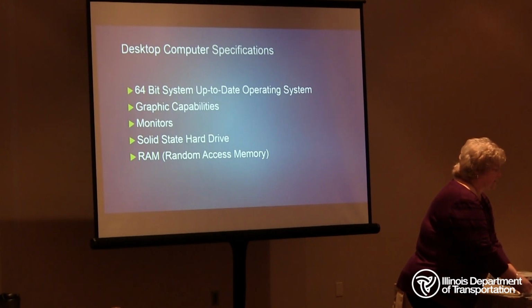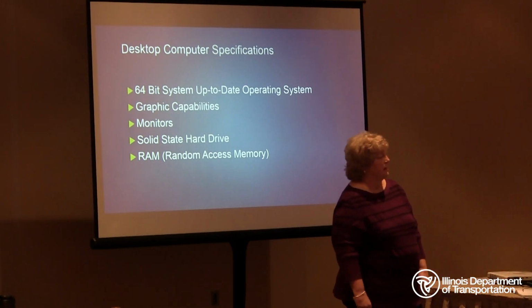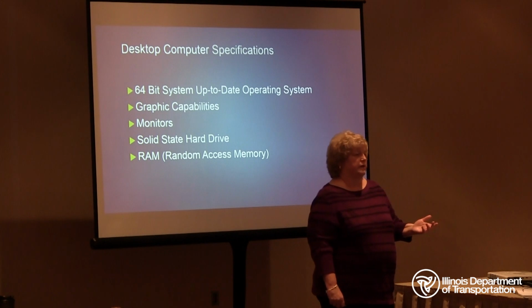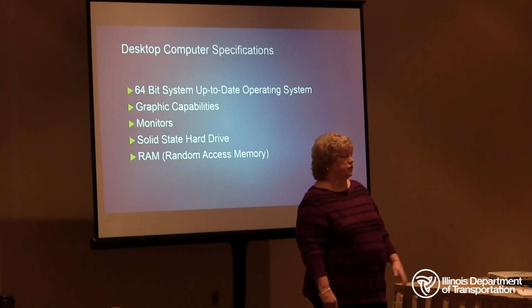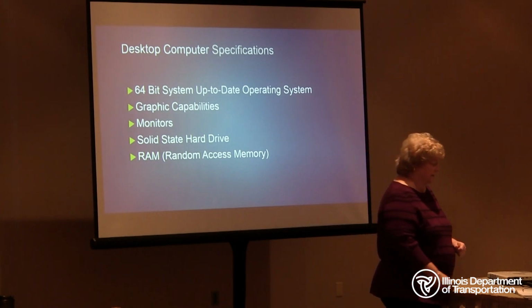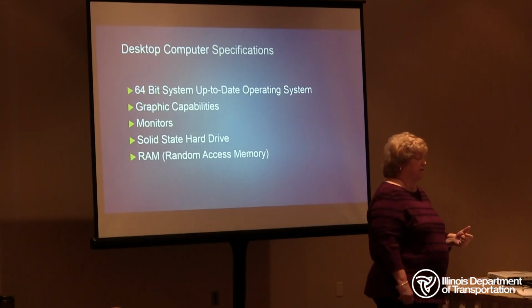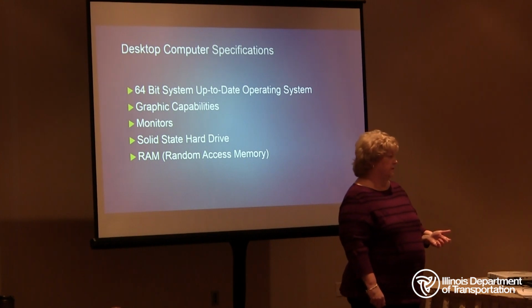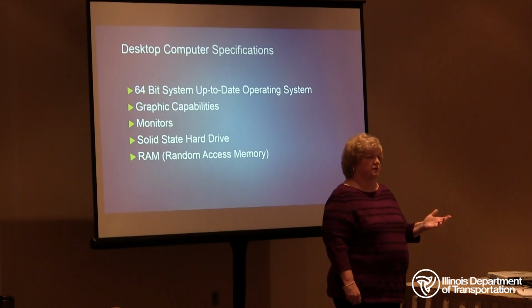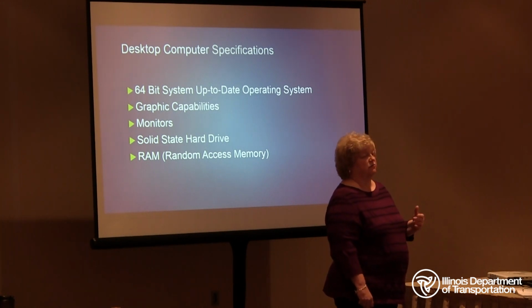Looking at the desktop computer specifications, I did some research online, and we also talked to California, who's been using LIDAR for a while, and they recommend a 64-bit operating system, good graphic capabilities, monitors with high resolution, solid-state drives, and as much RAM as possible. For the solid-state drive, they recommend at least a 500-gigabyte drive. SSDs have faster access speeds, and they're not as easily corruptible due to the lack of magnetic medium.